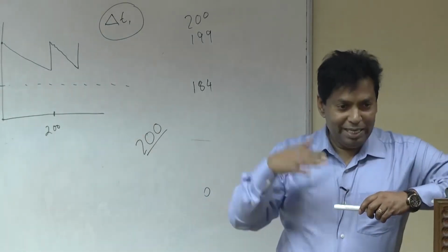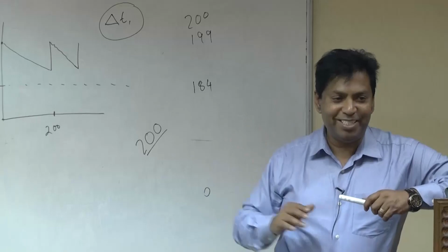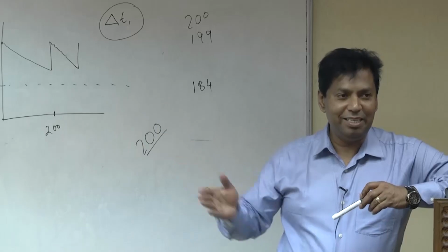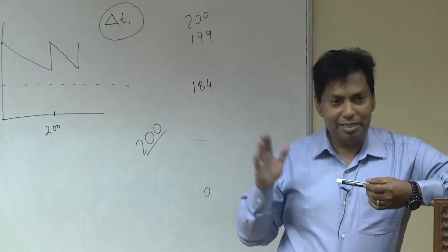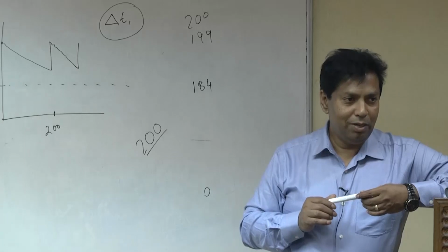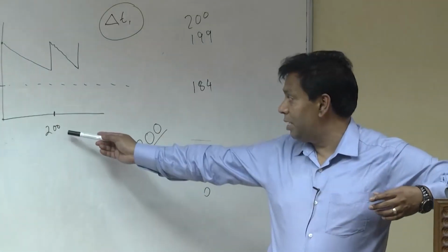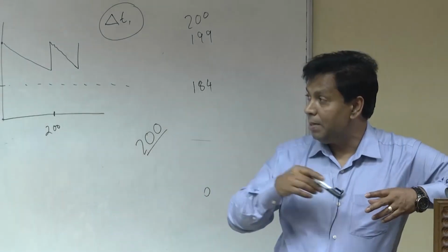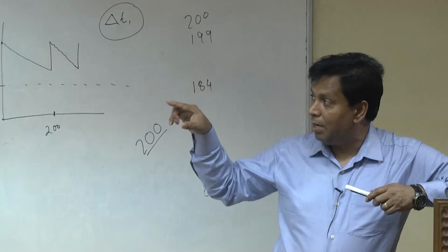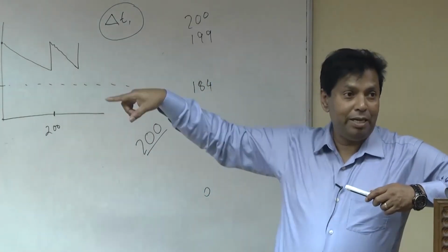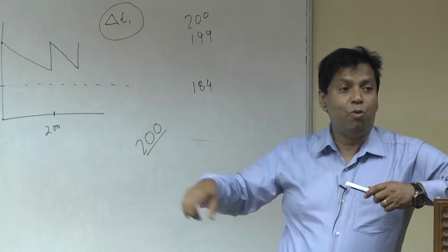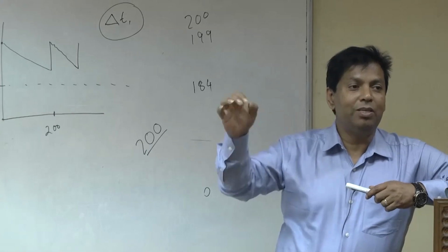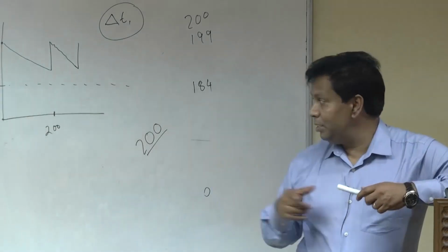So he is so lucky that his solution is converging very nicely, but it is not always the case. It is a very simple geometry, so it is easy. But when you are working with complex geometry, it's sometimes difficult. And this number of iterations actually fluctuates. For his case, with the profile he applied, you see the velocity pulsatile is high somewhere. There is a very big peak. I think at that time it will take more iterations. So it is not fixed that it will converge within 20 or 25 iterations. It will fluctuate.